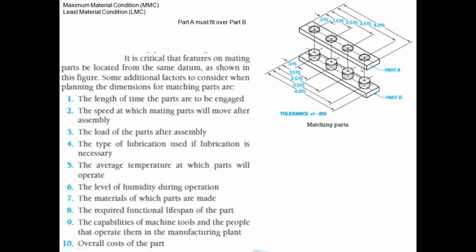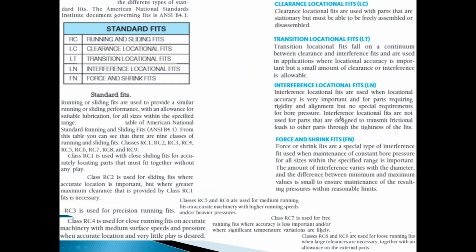As you can see from this matching part here, the tolerance is only plus or minus 0.015. If your error happens to be greater than this number or less than this number, then this hole may not fit onto this shaft.